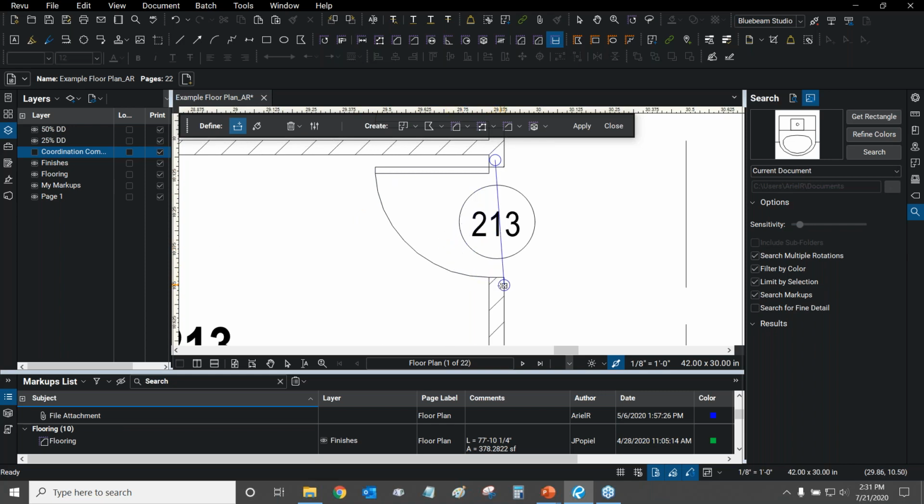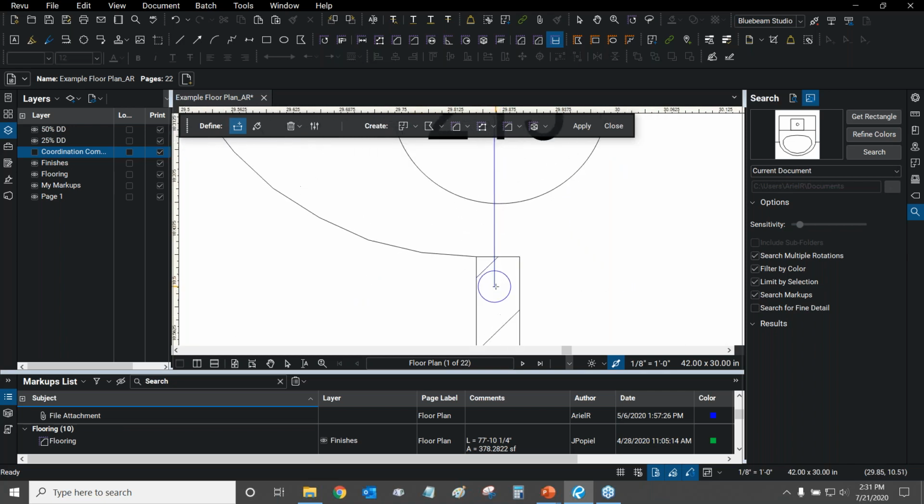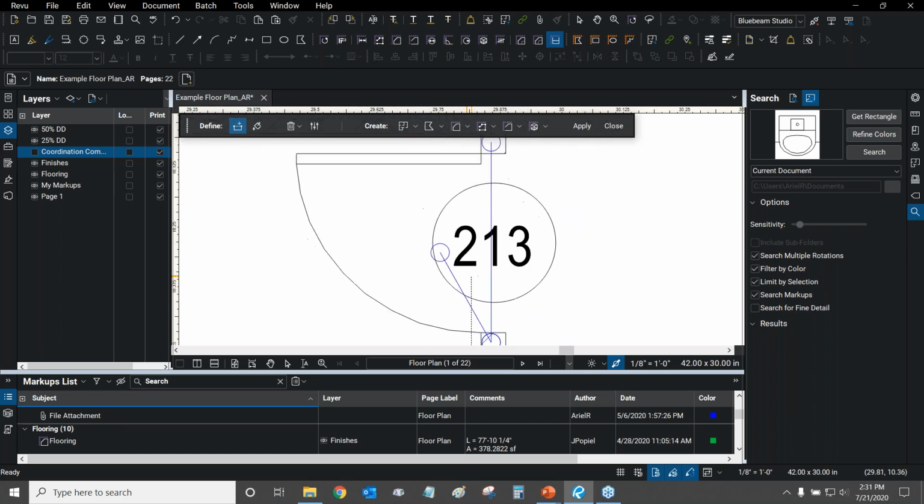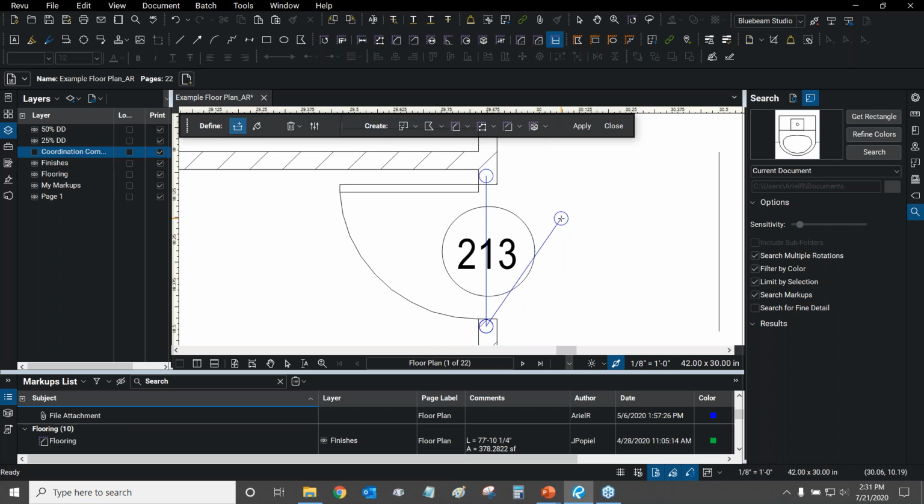So in order to make a straight line, I'm going to hold shift while I do it. That activates the 4 cardinal directions and 45-degree angles. Quite nice. So I'm zooming in while holding shift to make sure I get a nice boundary right there. Little gaps like this don't make much of a difference. You can have a few gaps, and I'll show you guys how to fix that after the fact.